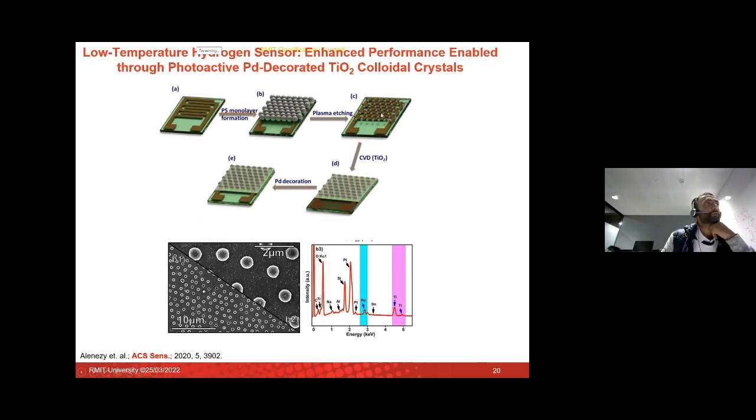We etched it as we've been doing, deposited titanium on our surface, and heated the titanium up to make it crystalline, so that the polystyrene escapes the structure. So what you're left with is a shell structure of titanium colloids. Okay, so these colloids are all shell. It's empty on the inside.